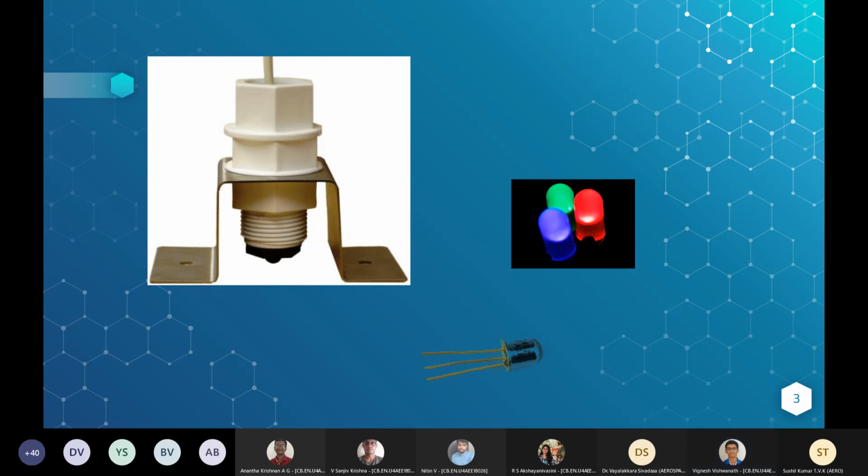But once the fluid starts leaking, the refractive index also changes, and due to the leak the intensity will increase, because now there is loss of fluid, so the intensity of light detected will increase. This transistor can be connected to a sound alarm or something inside the car. So when there's a leak, this will be detected and it can give off a sound alarm which will give a warning to the driver.